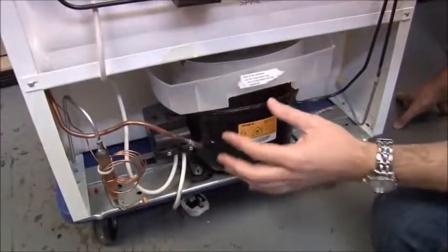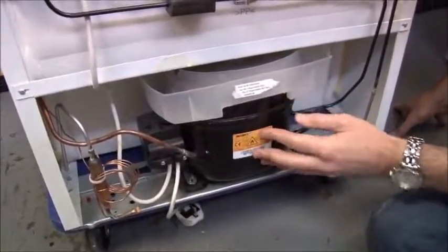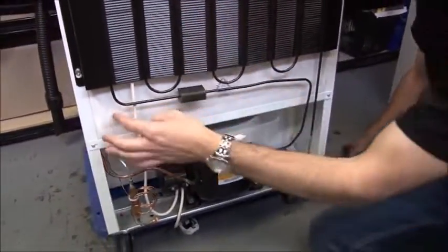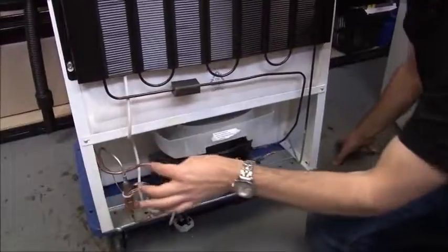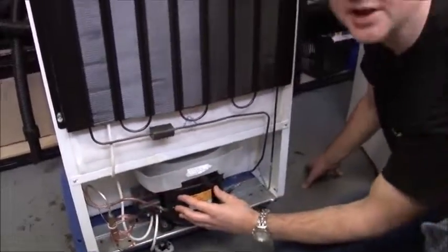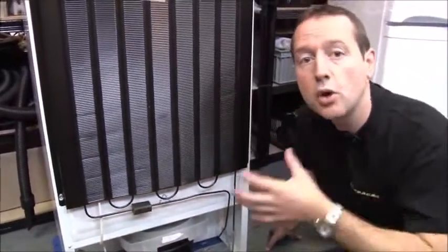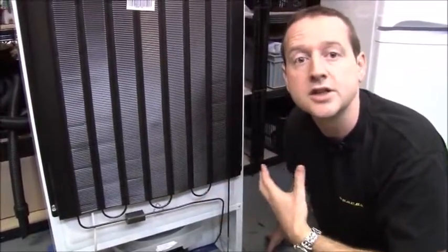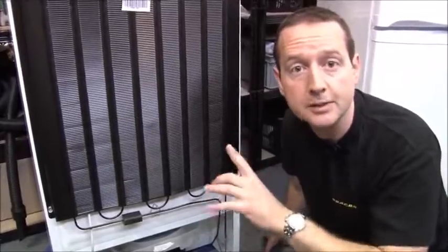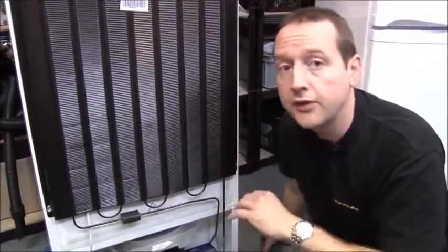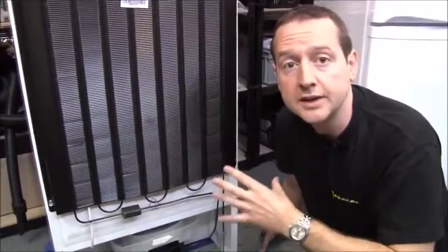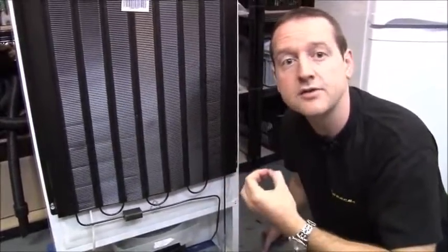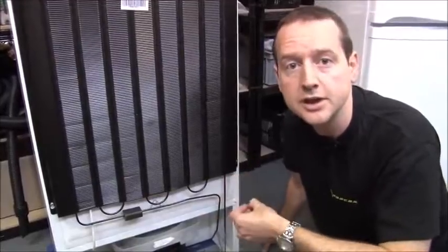It's essentially an electric pump which is pushing a refrigerant around a closed system, first along the outside of the fridge, then the inside of the fridge, before finally returning back to the other side of the compressor to continue the cycle. Now in the old days they used to use ammonia as the refrigerant, and that was quite toxic. They then changed to Freon, which you may remember is the stuff that did the damage to the ozone layer. This fridge freezer uses isobutane. It doesn't really matter what the refrigerant is, it just needs to be a substance that can easily turn from a liquid to a gas and back to a liquid again.